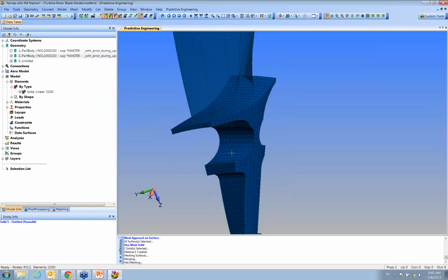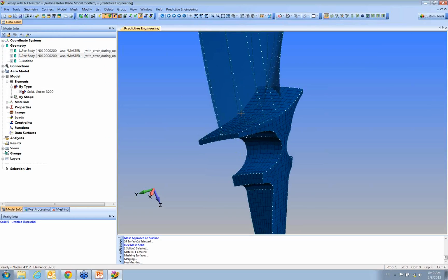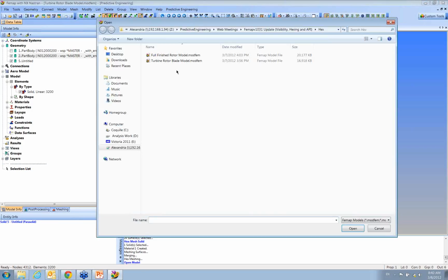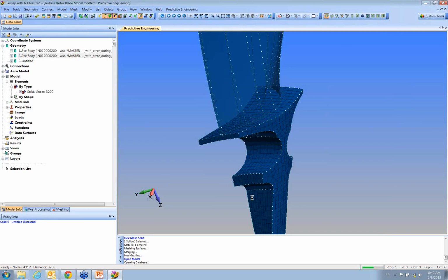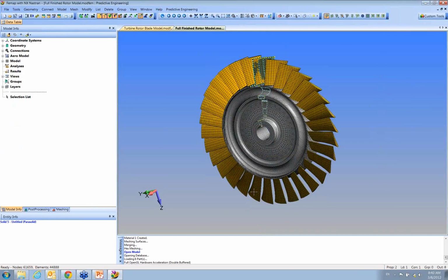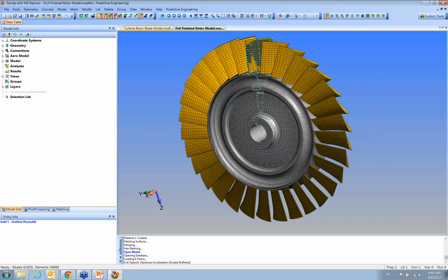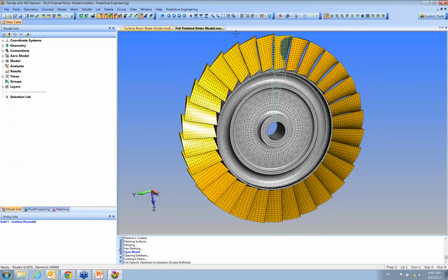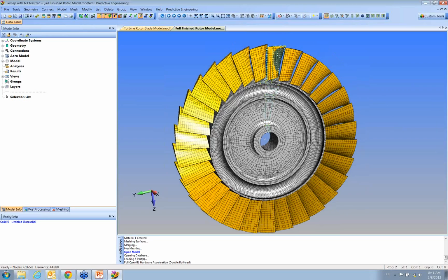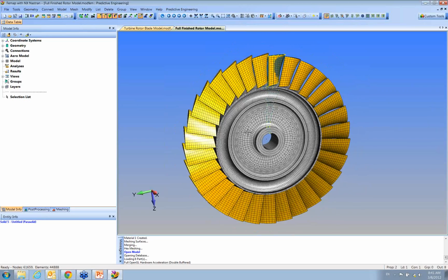Is that you can say, well, wait, you didn't do the blade. It doesn't count. Well, let me show you where it goes. And let's go to the full model. And this is for a LS-DYNA burst simulation where in aerospace this is a turbine, this is 8 inches in diameter, and it's designed to burst at 55,000 RPM, and you have to contain the fragments of the titanium rotor disc. And so you have to have a very economical model to do the simulation.